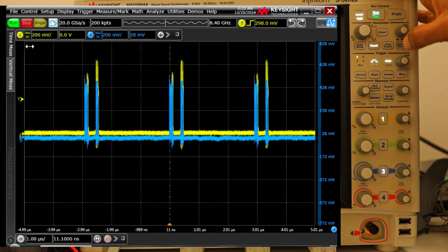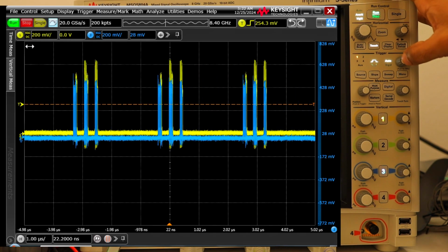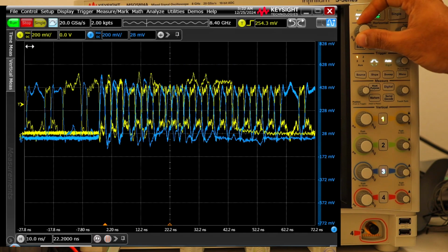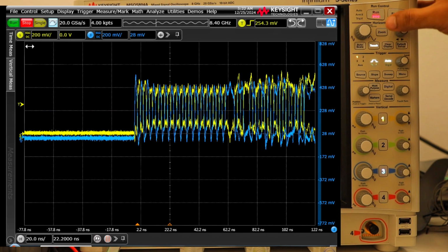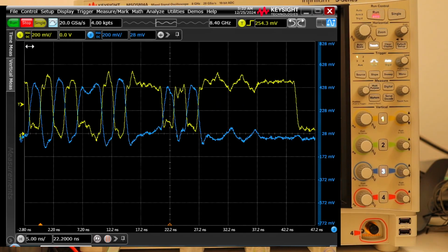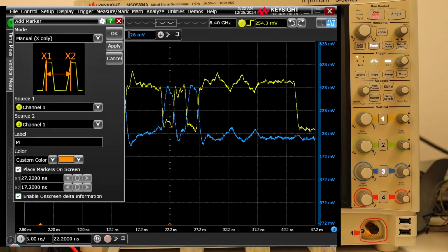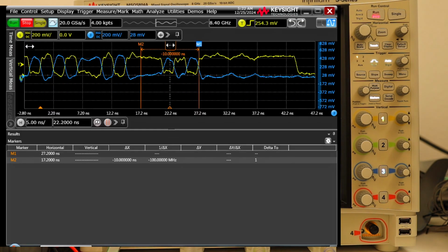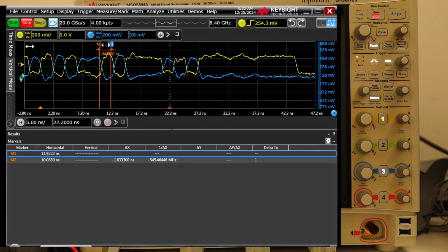Let's zoom in. You see, this is the USB HS transmission. This is fast stuff. If you want, we can analyze and set a marker there. Okay, so the fastest time is something like this. Starts from there and goes up to here. So you see this is around 480 megahertz. Of course, this is 480 megabit per second. So this is what you see as a delta on the pulse, and it is really USB HS. And we will remove the markers now.